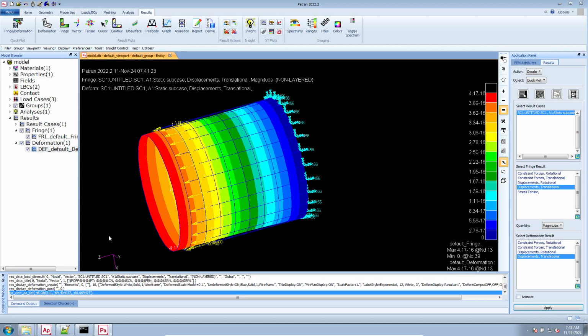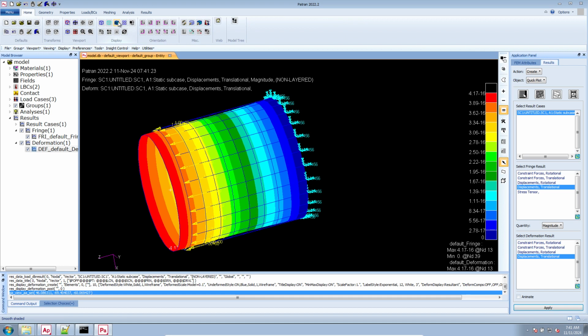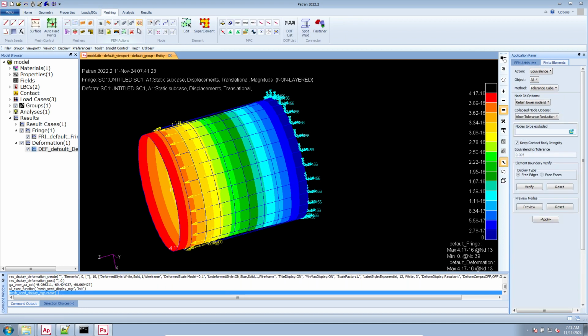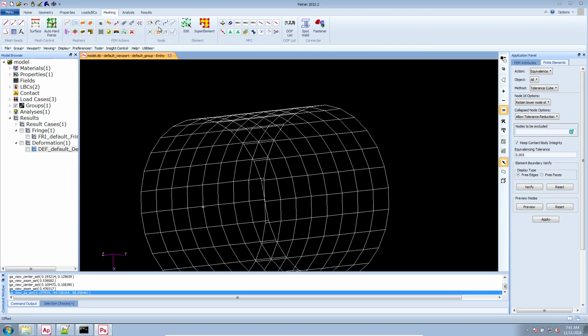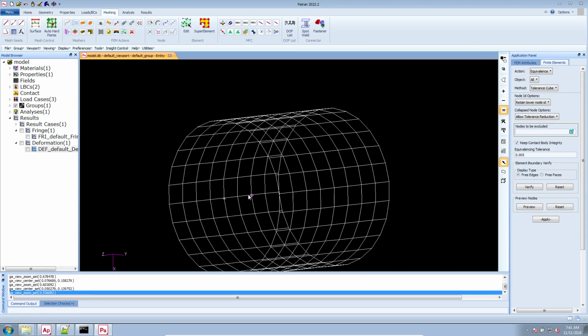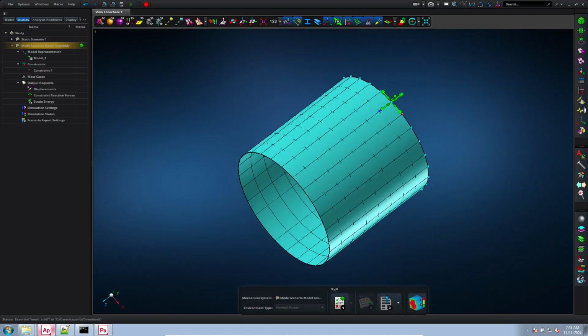I know that was a lot to cover, but I realized that if you have the question about the equivalence option, you most likely have a lot of questions because you're relatively new to the software application. So to quickly summarize this entire video, if you have cracks in the mesh, make sure to use the equivalence option to merge those duplicate nodes. And also, if you want to create geometry, edit geometry, and mesh it, I highly recommend using a separate tool for that, like MSC Apex.